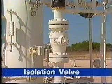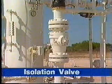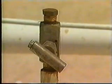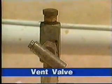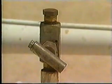Isolation valve. Isolation valves provide a way to isolate the meter tube from upstream and downstream line pressures. Vent valve. Vent valves allow the meter tube to be depressurized after it has been isolated from upstream and downstream line pressures.